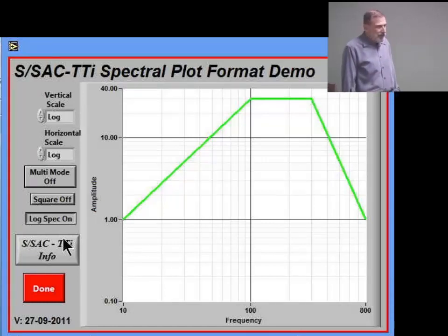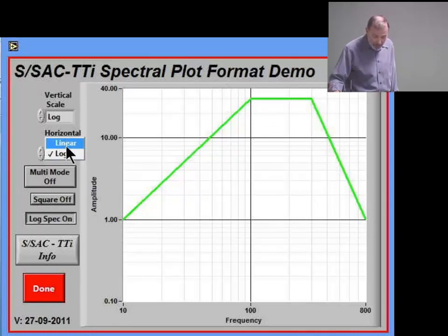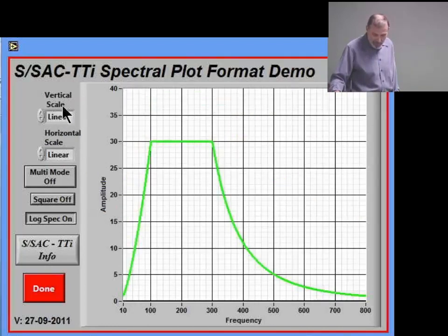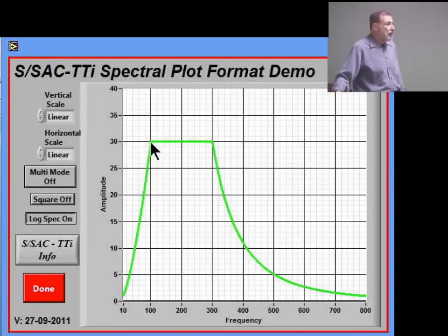Well, if the spec is straight lines in log space, it's not going to be straight lines in linear log space or linear space. Actually, the only thing that turns out straight in both is flat, obviously, or something that's at 45 degrees. As it turns out, if it's going up at 6 dB per octave, that winds up being a straight line in either one. But how often do you see that?